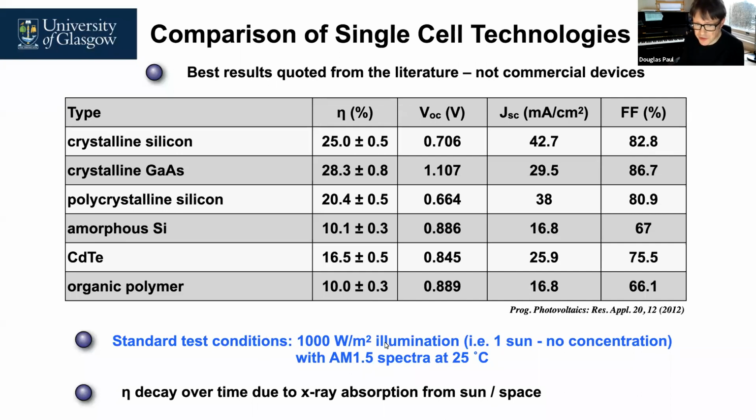So that's the peak you're going to get of about 250 watts per meter squared of photovoltaic cells that you have out. Now, houses typically will be a number of kilowatts that you require at any one time. So if you need to get 5 kilowatts as your power using photovoltaics, you can see that that's going to be 20 square meters of silicon photovoltaic cells if the efficiency is 25%. So that's how this works.